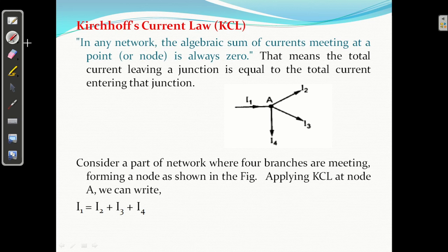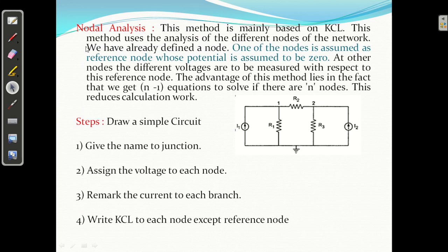Now I am going to talk about nodal analysis. What is nodal analysis? The other name of this method is node voltage analysis. This method is based on the KCL, Kirchhoff's current law. What we have to do is find the node voltages. And how many nodes are there? This is node 1, this is node number 2.